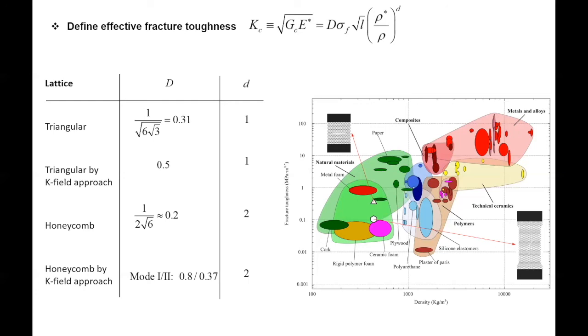Now, I don't like the infinite domains and infinite cracks and no cracks, because we just don't have any practical applications, right? And it's not just because of our 3D printers. We use those in sandwich structures, things like that. Even with manufactured foams, it's very easy to have 50 cells in your structure. And with 50 cells, you should consider that as a material instead of a structure. So I believe that there is a continuum there, all right? My disagreement is with linear elastic fracture mechanics. I believe that energy is a little bit more appropriate, and that fracture energy could be the way to go. Now, is it